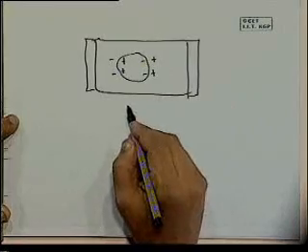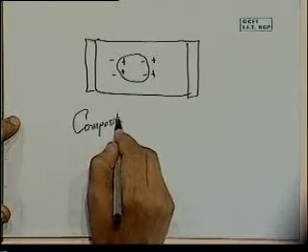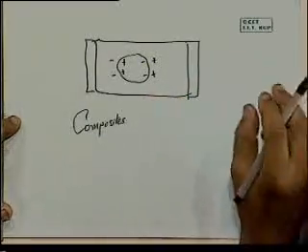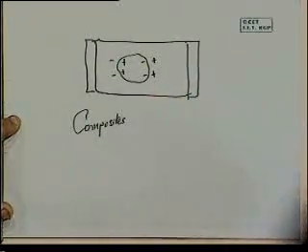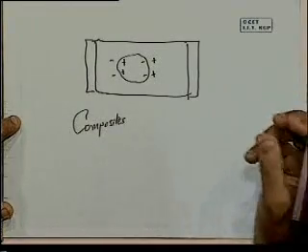A more common situation these days may be where we have composites, where you have a matrix and inside it a dispersed phase, small particles of a dispersed phase. Now, at each of those boundaries where we have the dispersed phase in contact with the matrix, the same phenomenon will occur. So if there's dielectric behavior there, then that adds up to the interfacial polarization.